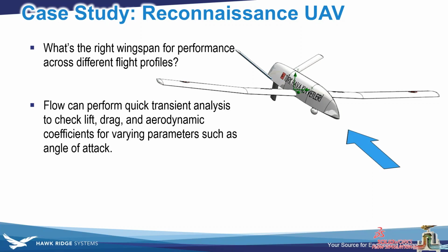So we're going to look at how you would do an aerodynamic simulation in Flow Simulation. And of course, we would be able to do that not just as a steady state simulation where we've got constant airflow, but also as a transient analysis. That would be useful if we wanted to study something that was changing over time. Maybe, for example, the wind speed picking up.